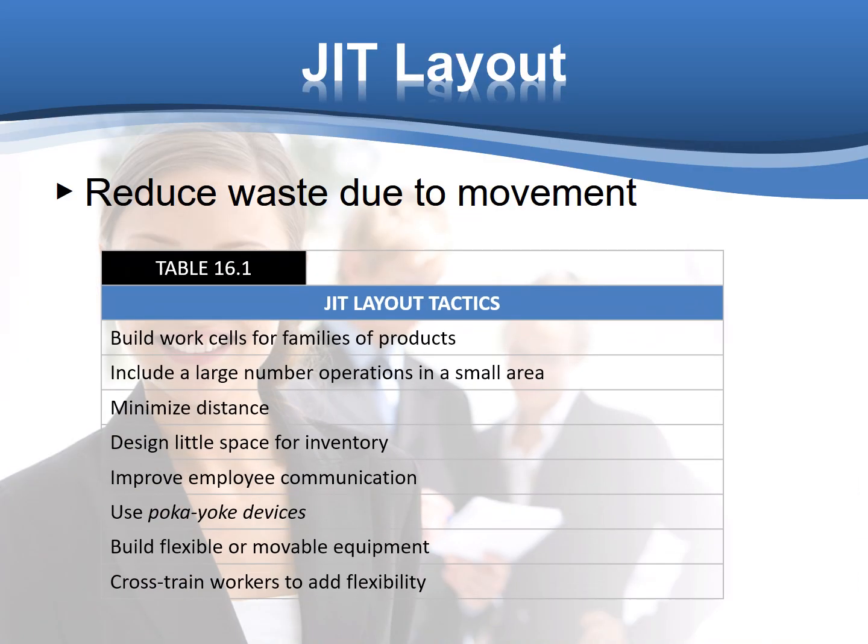Just-in-time layout requires that you reduce waste due to movement. You build work cells for families of products and include a large number of operations in a small area, minimize the distance in between, and have little space for inventory so the inventory doesn't clutter up the floor. Improve your employee communication, use poka-yoke devices, and cross-train your workers to add flexibility.